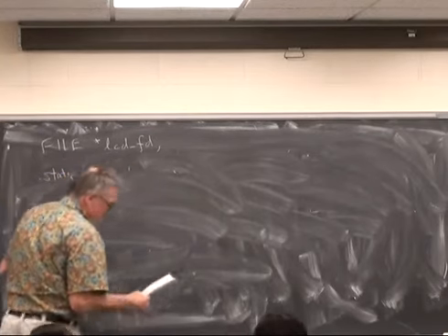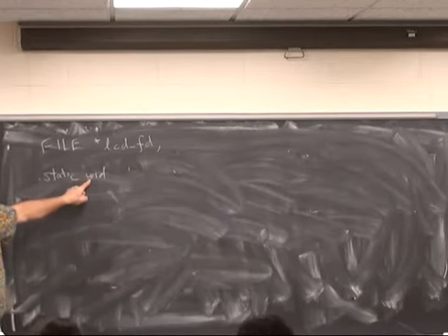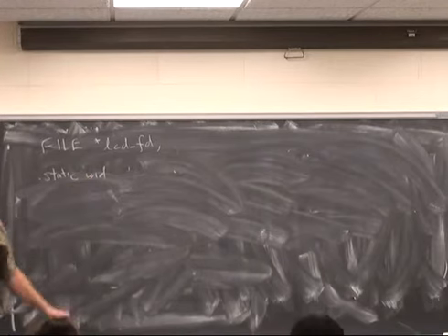And of course, if this is an interrupt service routine, it must be of type void, right? Because interrupts cannot return a parameter because there's no place to return to.